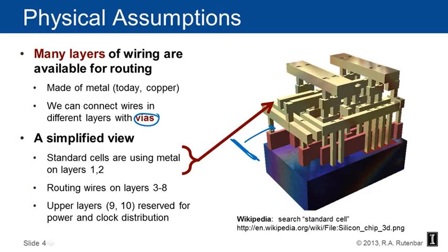So that's things like this. And things going in this direction like that would be the metal 2, and then there's some other stuff happening going again in the other direction up here. That's some metal 3. The standard cell's internals would be routed on metal 1 and 2, maybe metal 3.